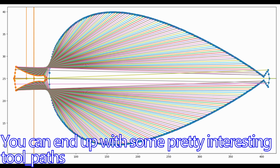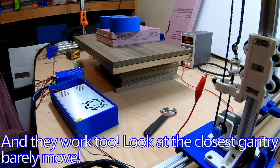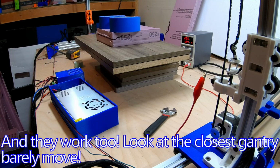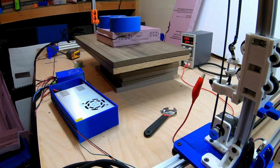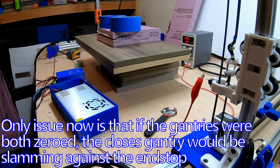And before we get to the actual cross-section part of this, I wanted to show some of the interesting cuts you can end up with, especially if you don't well constrain the tool paths. So currently I'm constraining it so that if the leading edge ends up forming an extrapolation that ends up going below the x-axis, so into the negative quadrant, it will offset the entire cut path so that you don't end up receding past zero.